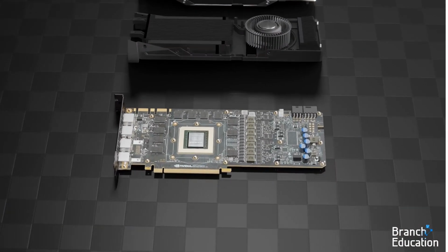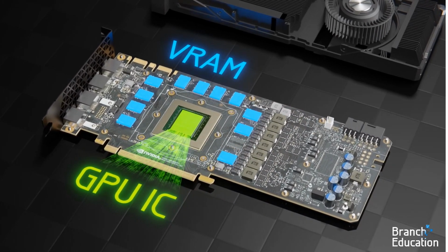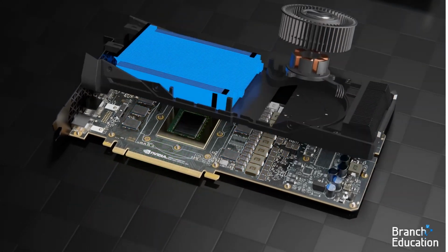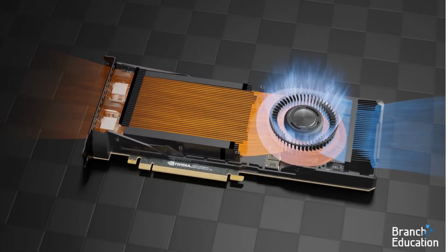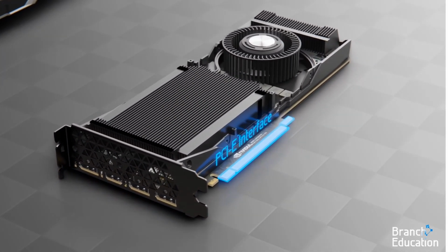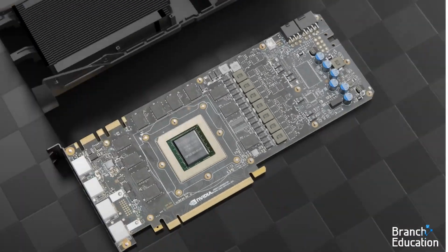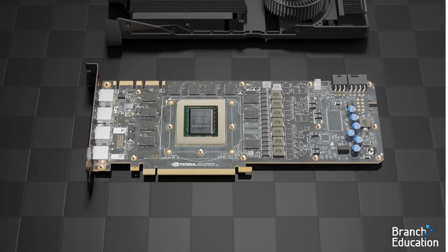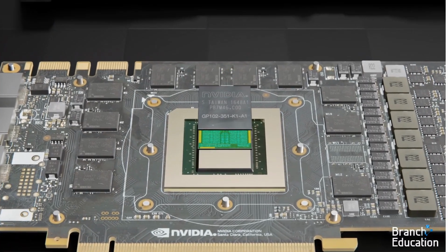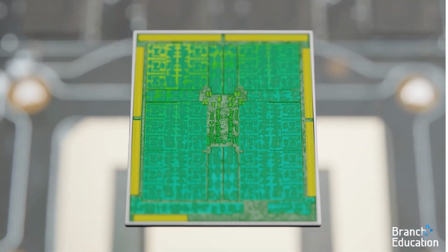Let's have a look into the graphics cards and their major components. This is the GPU IC surrounded by VRAMs and VRMs. VRM stands for voltage regulator module. Above that, we have a heatsink which cools down our GPU. It has a couple of ports, DisplayPorts and HDMIs, and the power connectors used to power the graphical processing unit. The graphical processing unit requires a heavy amount of power, ranging from 0 watts up to 200 watts depending upon the workload we are putting on it.